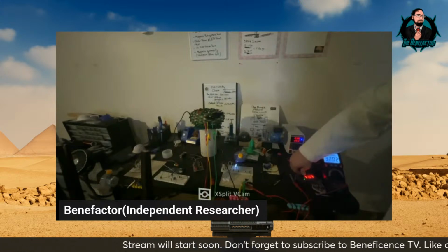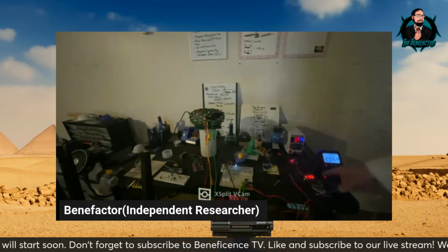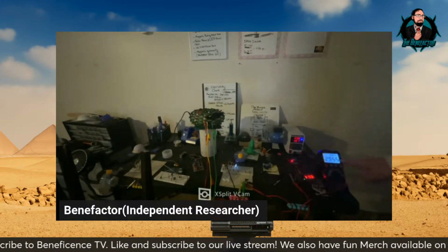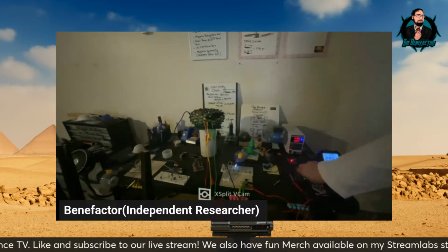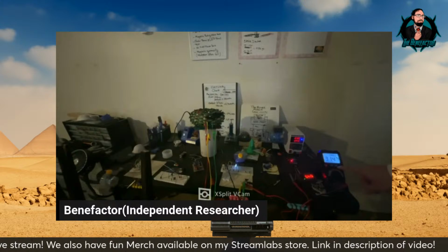I'll have to look up how to do it. I had to look up how to do this. So yeah, see, we just increased it to 61% duty, and it just kind of took a crap on us, right? Look at the sawtooth. That is closer to an AC signal. It's just not close.